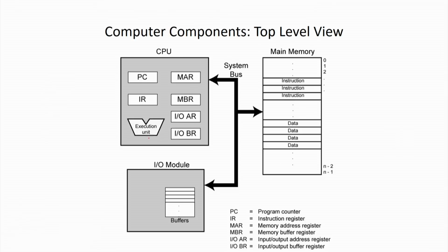To perform work, we have to bring the information from main memory. So, this memory will be connected to the processor. We call this the system bus. Through the bus we connect the memory. Already I have talked about how a bus is nothing but a connecting wire. Inside the processor also we have an internal bus, and through that internal bus we transfer information from one component to the other.